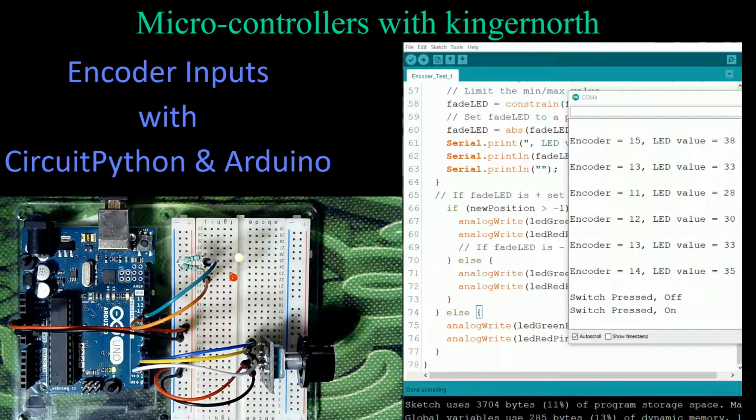So we're able to use the encoder to count up, count down, and we're also able to use the switch to turn it all on or all off. So we have a lot of variables that we can do with this thing. So now if you want to control that model train, that regular DC train, or that regular DC motor, you can now control it through this and just add on a transistor on the other side. Or an H bridge, you could feed it and there's your 2 power leads. The 2 leads that it needs are the 2 leads going to the LED. So now you have some flexibility. You can start utilizing this and come up with ideas on what you want to run. Works really well. Let's go look at the CircuitPython version of this now.